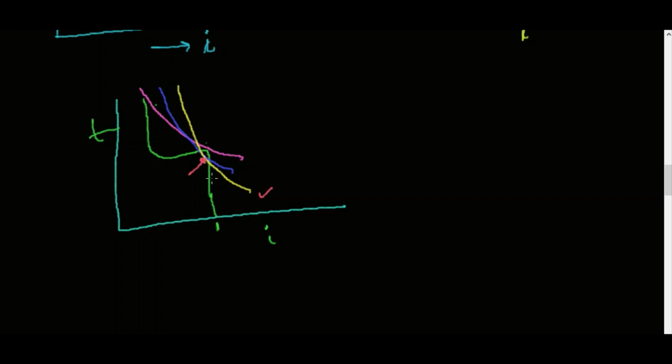During the starting of the motor, this relay will pick up and probably the circuit breaker will trip. So if we select this standard inverse characteristic, it may be suitable. Based on the downstream motor connection, the motor starting current, or the downstream relay coordination, we need to select which IDMT curve to choose, whether standard inverse, very inverse, or extremely inverse.